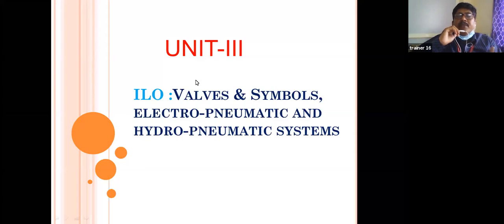will eliminate all the impurities from the air, right? And then it enters the compressor. There the air gets compressed. This much amount of air is sucked inside the compressor and compressed to a small amount. That means the volume decreases, the pressure increases, and the temperature increases. So the output of the compressor is high pressure, high temperature compressed air. To cool that compressed air, we have to arrange a cooler.